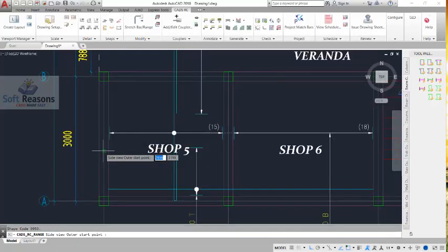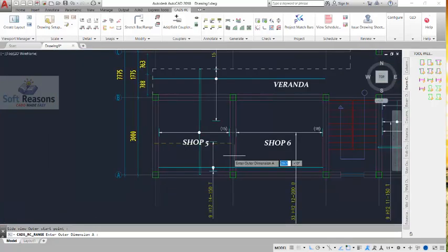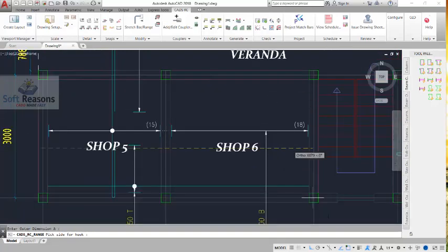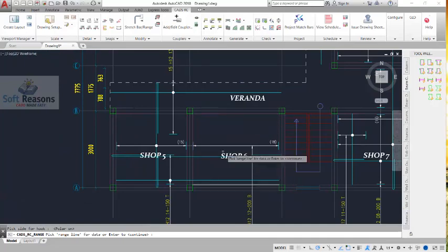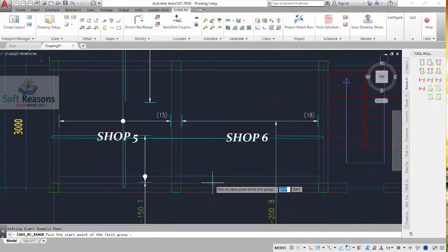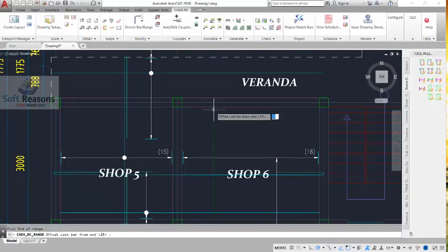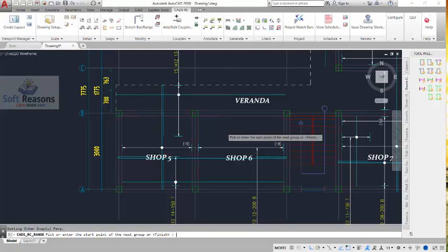So click in these provisions, pick this point, so press point of the bar, so take the bar all the way from this point, and then the length is going to be up to this point. Click that there. Okay, for the hook, take it upward, or activate your polar, take it upward and place it just like this. After which it's going to be spanning through from this point to this point. So just enter once and pick the group start point, 25 millimeters concrete cover, and then pick the end point, 25 millimeters concrete cover. Enter again, the spacing is 200. Enter again. All right, enter and finish it up right here.